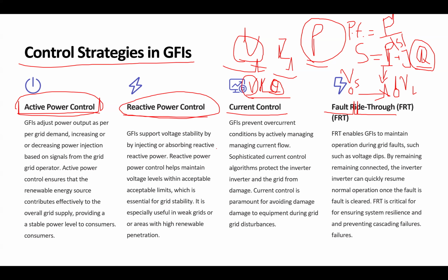Based on those loads, we calculate how much active power we have to inject to supply that load. And based on that calculation, using the formula that relates the active power to the phase of the voltages, we define our initial phase, in radians, not frequency, the phase of our PWM signal relative to the voltage that we have in our terminal.